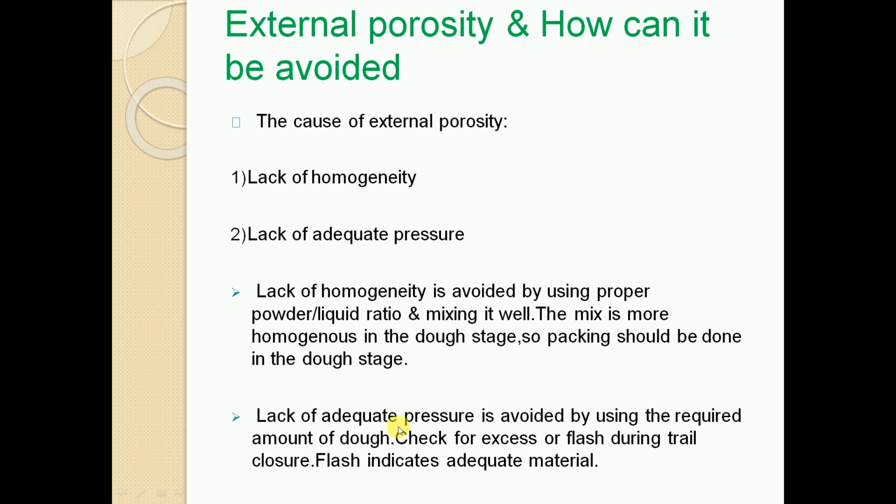Lack of adequate pressure is avoided by using the required amount of dough. Check for excess or flash during the trial closure. Flash indicates adequate material.